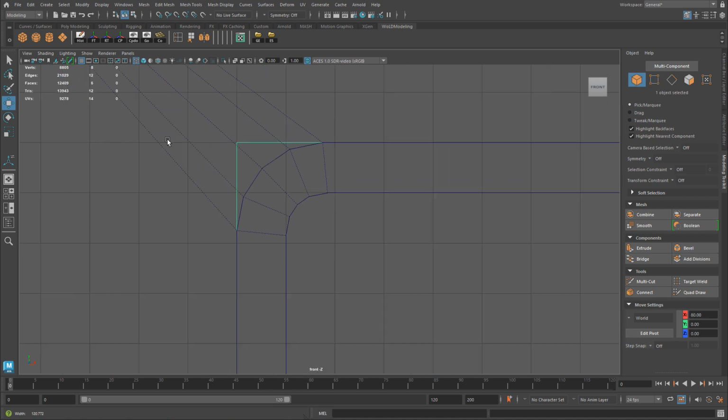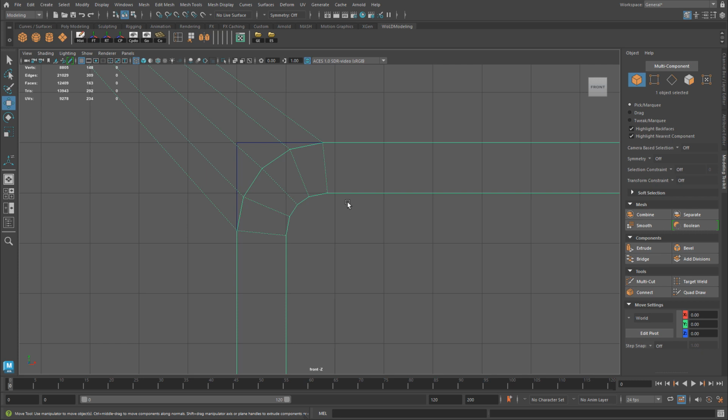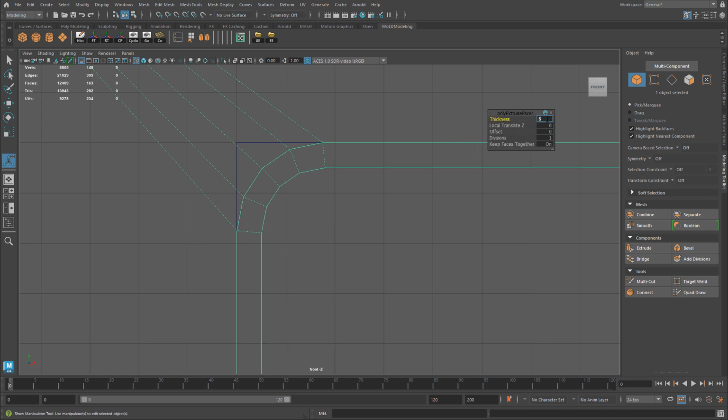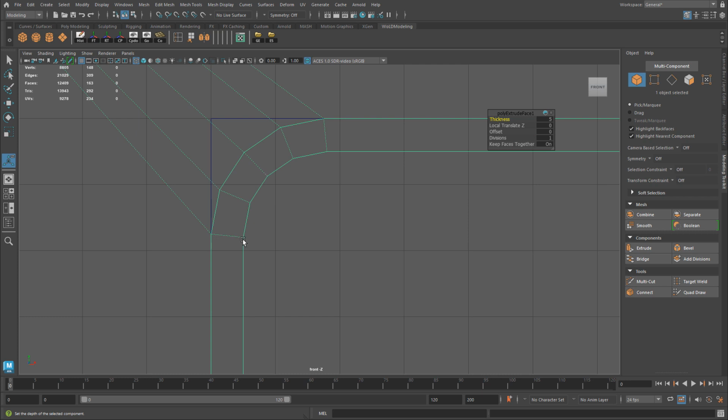So that means we'll need to resize the door, and for this door frame, let me bring back the menu. If you hit T for transform, this will bring back the floating menu of the last operation you used. So if I set this to 5, you can see I won't be able to align these verts right here to make them straight while keeping the outer corners curved.